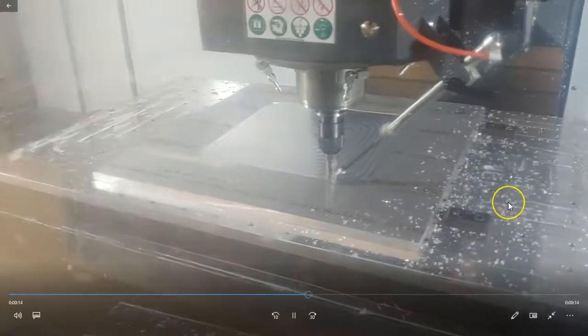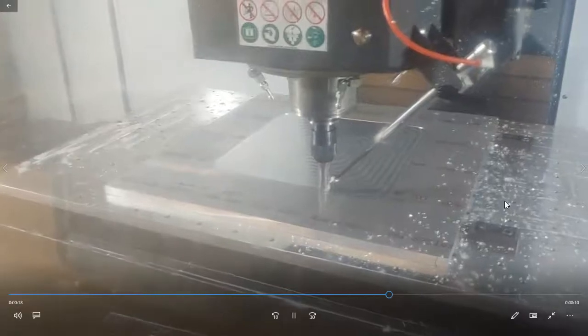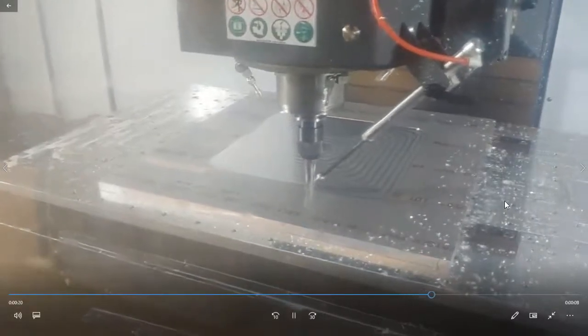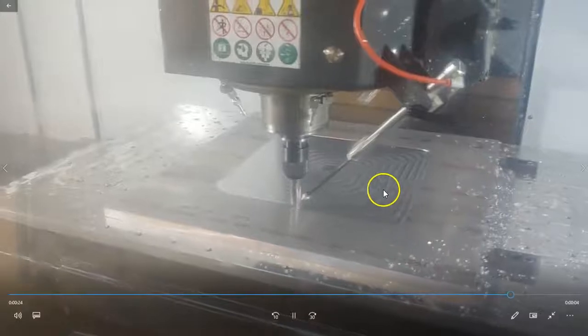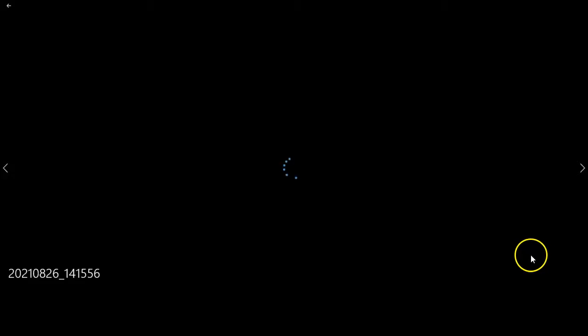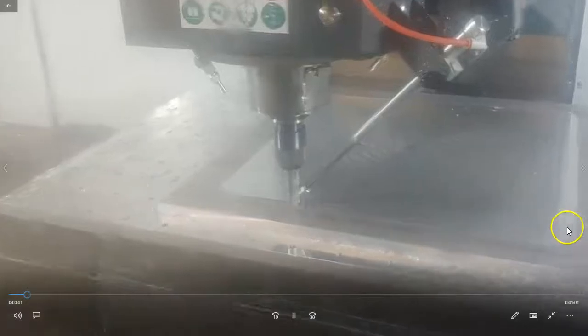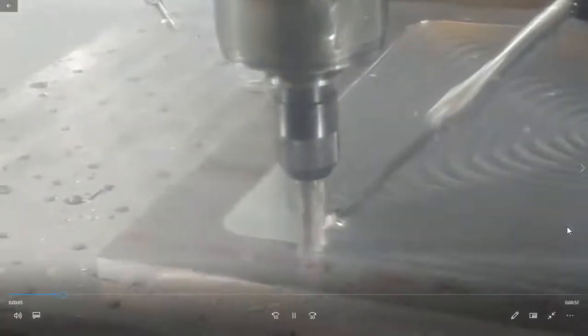So I'm running a small 1-inch, and I'm running it at a higher RPM and a higher feed rate. And that's going to ultimately affect the surface finish and the waviness. So 34 inches a minute. And the problem is that these clamps, unless the material is 1 inch or taller, I run the risk of milling into my fixture, into my clamp, rather than